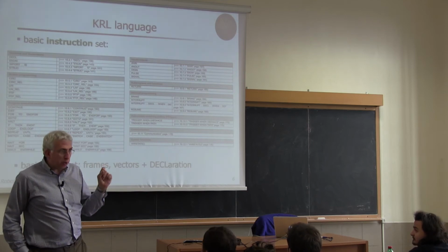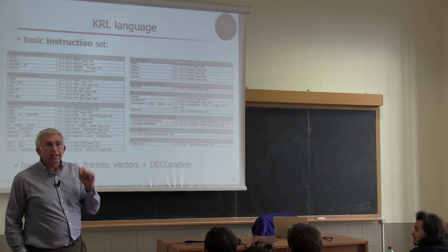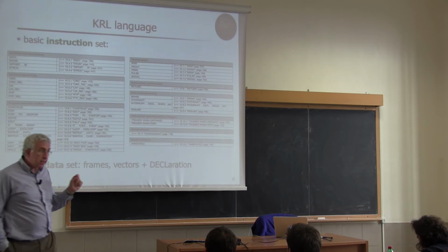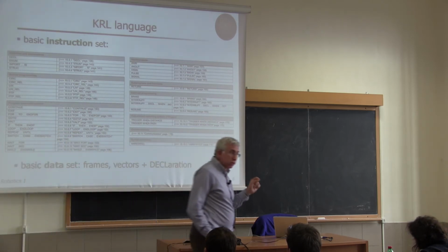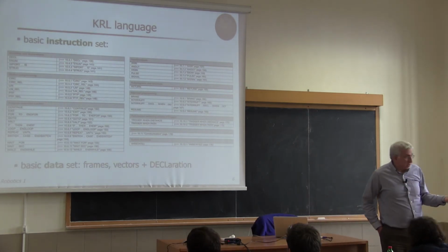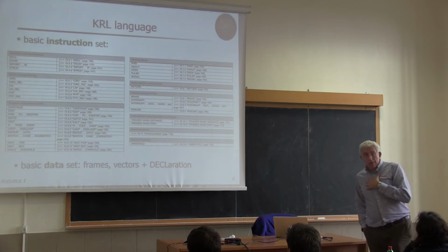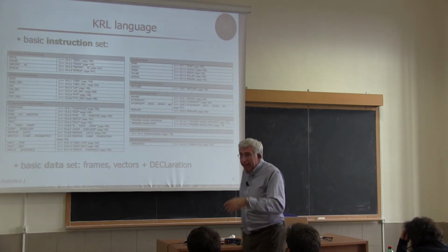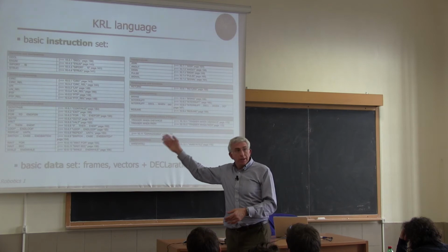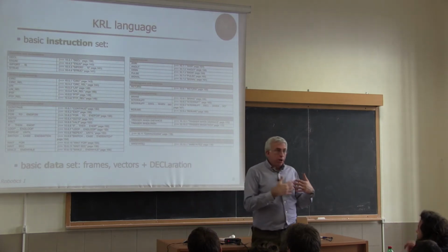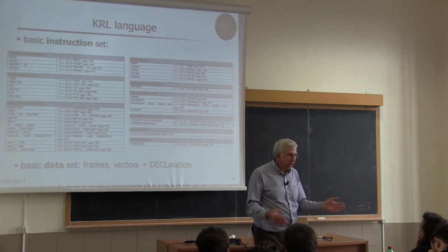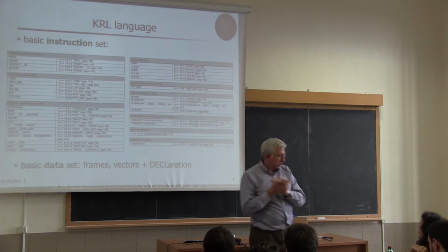PTP stands for point to point, and it's a motion which is defined in the joint space, while LIN and CIRC are motions which are defined in the Cartesian space, along a linear path or along a circular path. We can combine these and make much more sophisticated motion, or program ourselves some strange motion which is not a line and not a circle. But if we want to use their controller, our program should then decompose, no matter how complex the path that we have defined, into these elementary paths so that we can call their own laws.